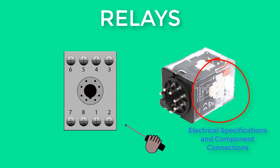Typical relays have electrical specifications and circuit connections printed on the side of the relay enclosure. Specifications typically include coil voltage, contact current ratings, and relay base terminal connection numbers.